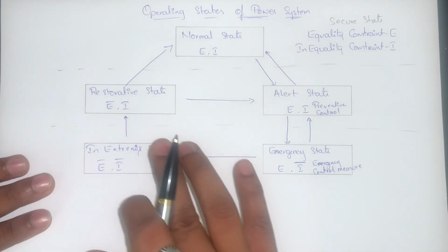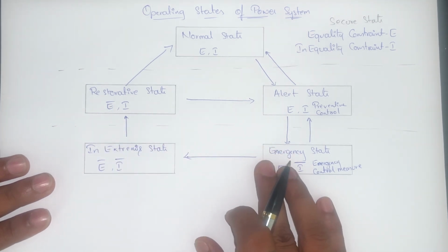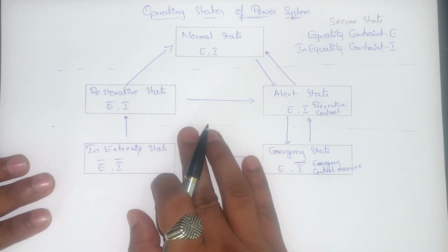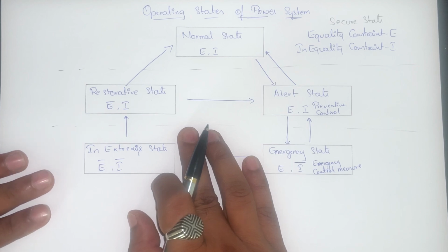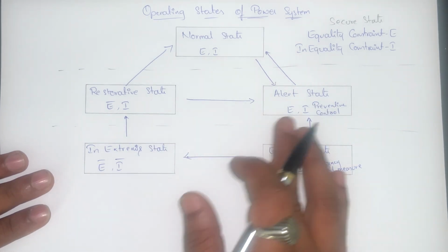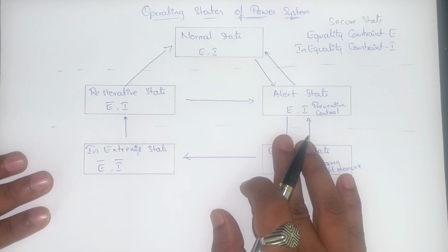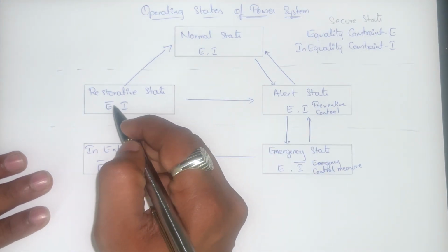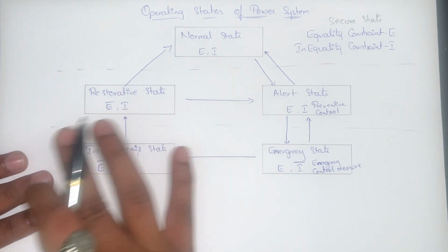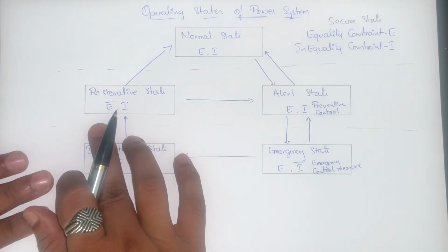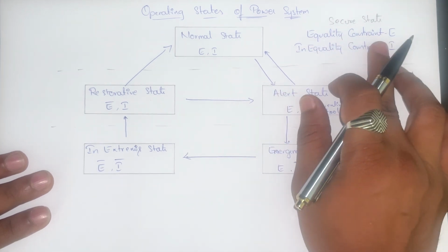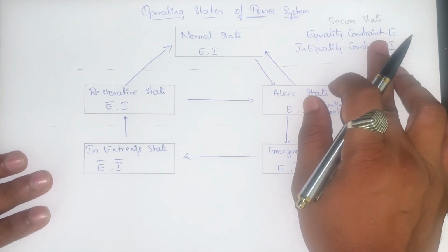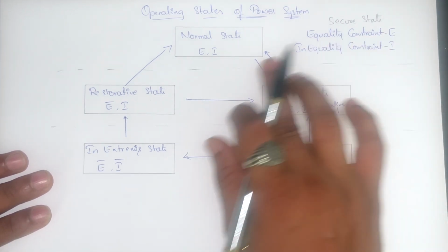Okay, we are only taking care of the limits on the generators, the voltage limits on the transmission line, the current limits or the transformer limits on the system, and the power balance has not been restored here. Okay, and the equality constraints discuss the power balance constraints between the generator and the load.